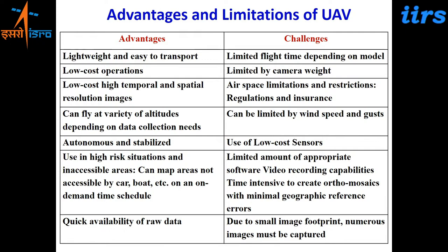Once you have flown the flight, the drone is brought back to the ground and the data is available. Challenges again are limited flight time. Some drones can fly only for 20 minutes, some 30, 40, maximum 1 hour. So based on that, you cannot have a larger area coverage. It is also limited by the camera weight. Depending on the weight of the cameras, you can install only those sensors.